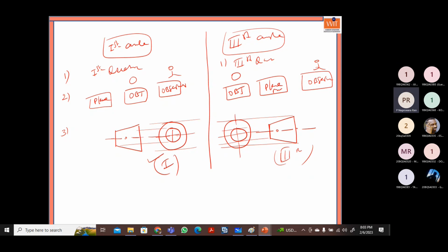So we can prefer either first angle projection or third angle projection. We are not preferring the second angle projection and fourth angle projection because the views are merging. Either front view, top view, or any side view, they are going to merge with each other. Okay, so today we learned basically the meaning of first angle projection and third angle projection, where we use which one, and what the symbols of the first angle projection and third angle projection are.